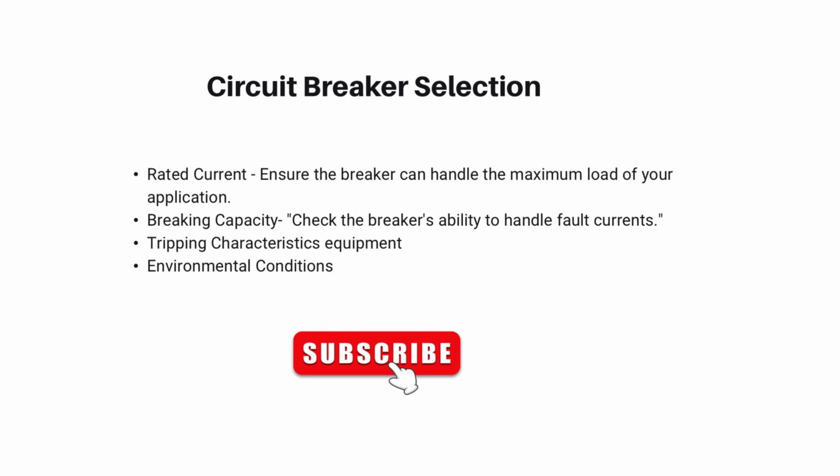Then the other factor that you can also consider is the environmental conditions. You have to consider the temperature, humidity, dust levels, and so on of your installation site. All these determine the selection of the circuit breaker.